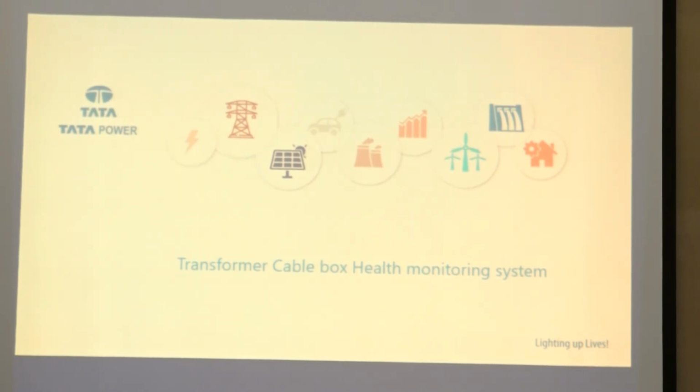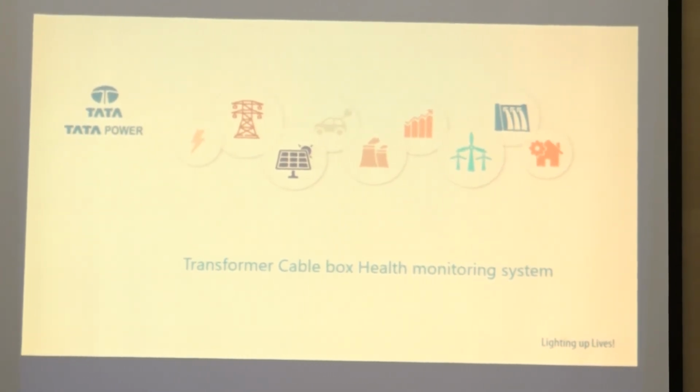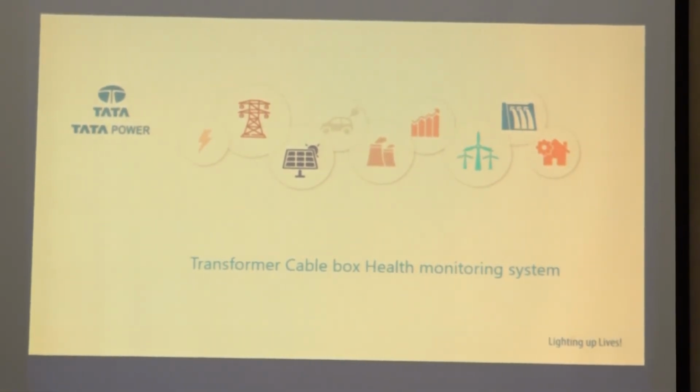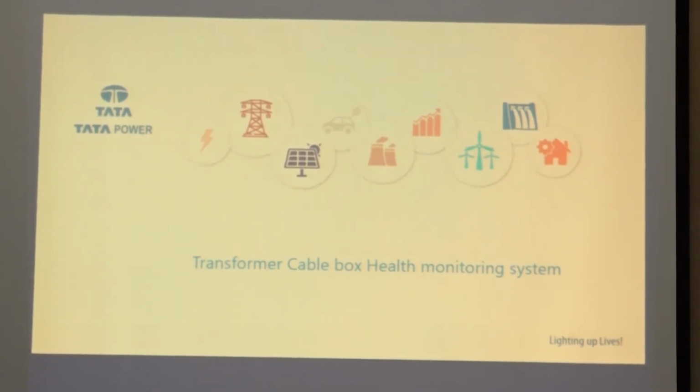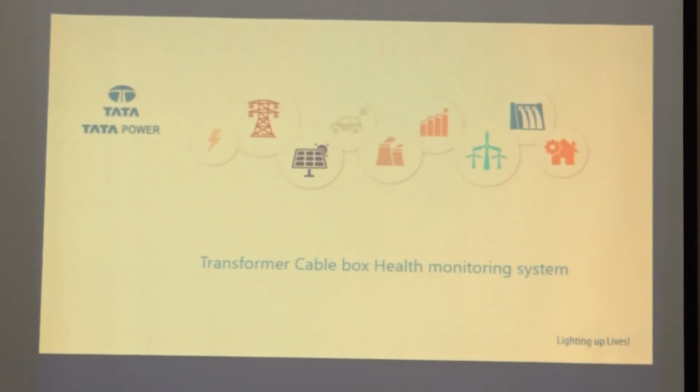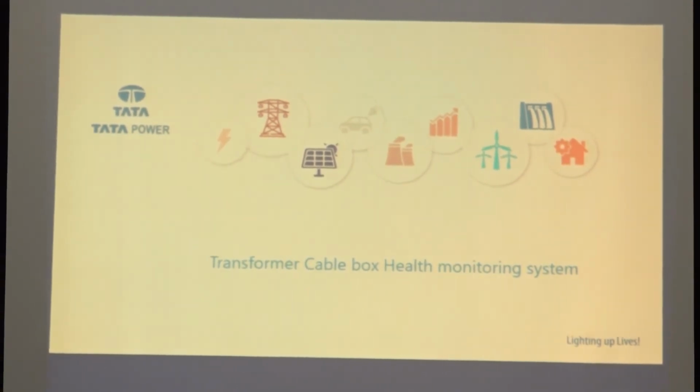It will cool it down, and when water droplets are made, it will remove the moisture through a pipe. Along with this project, we have installed the dehumidifier also. So this is for condition monitoring of the LT cable box as well as whether any water droplets are made inside the cable box.